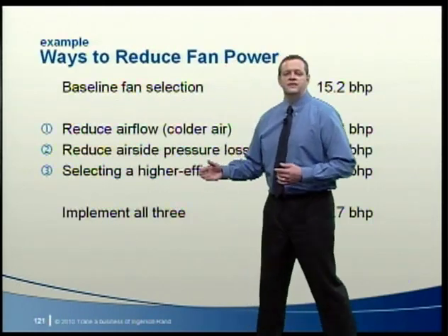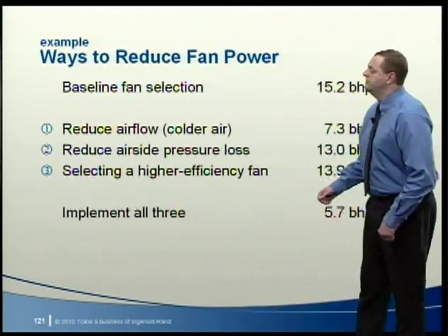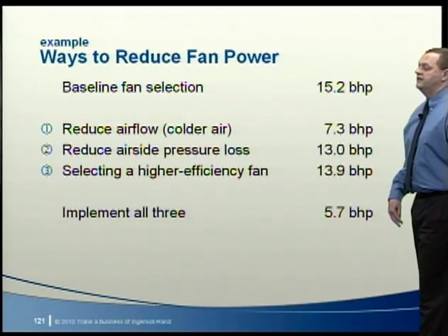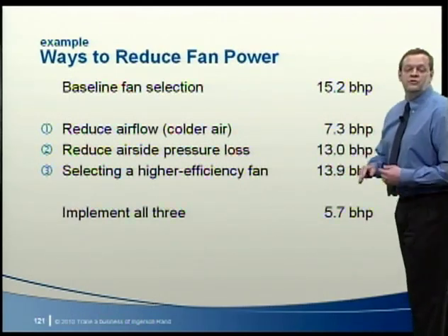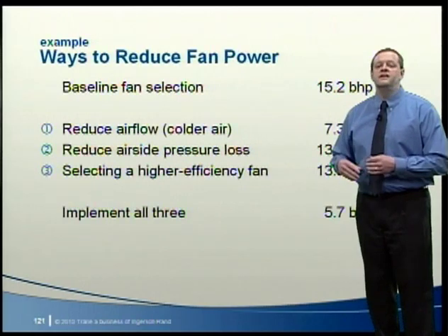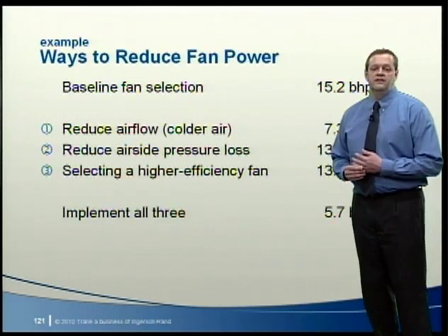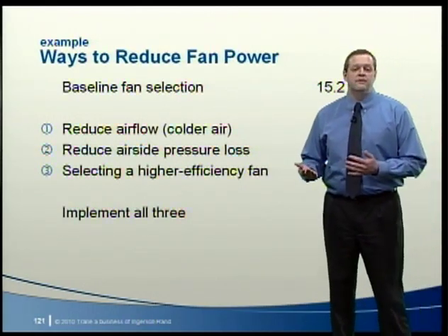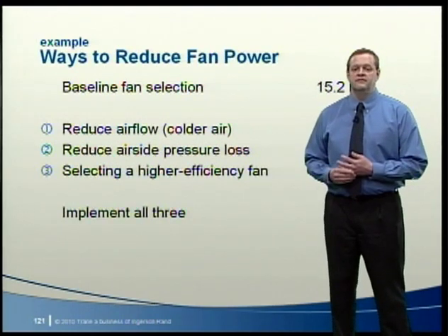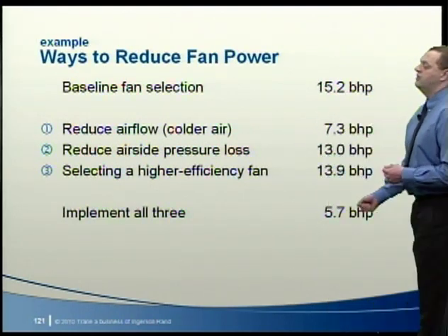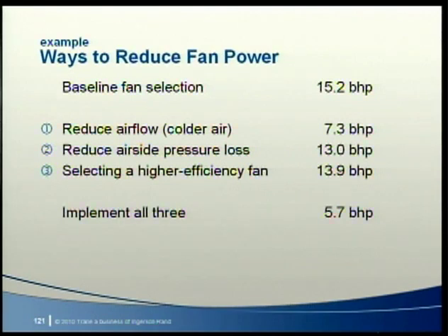So if you have a choice, the biggest reduction comes from reducing supply airflow. The next biggest comes from reducing airside pressure losses, then comes selecting a more efficient fan. Don't just focus on fan type or you'll miss these bigger opportunities. Of course, you could choose to do all three and achieve even more fan power reduction.